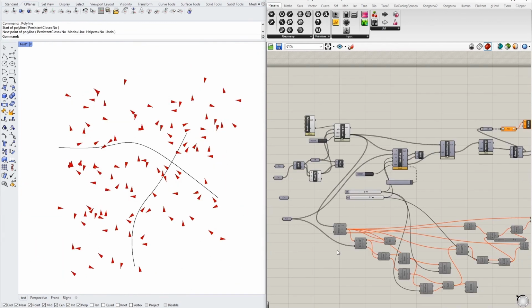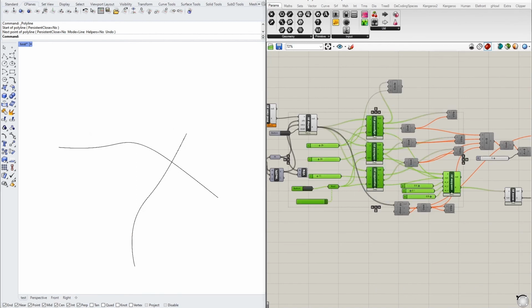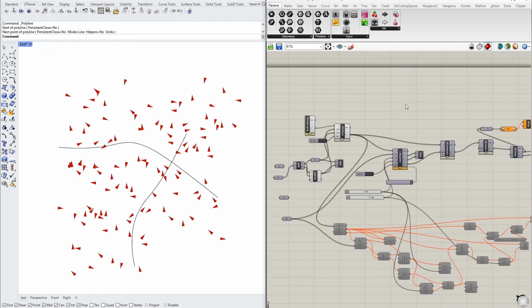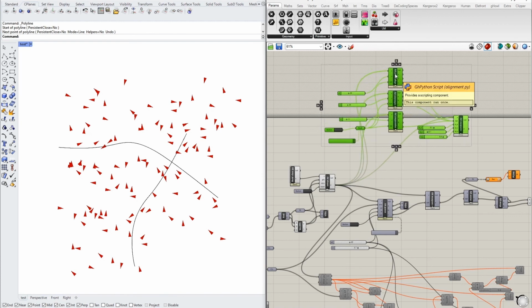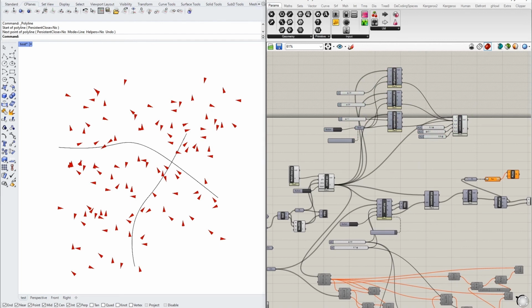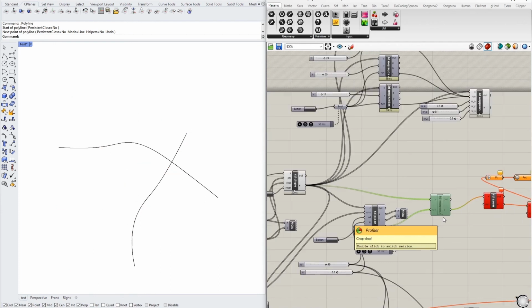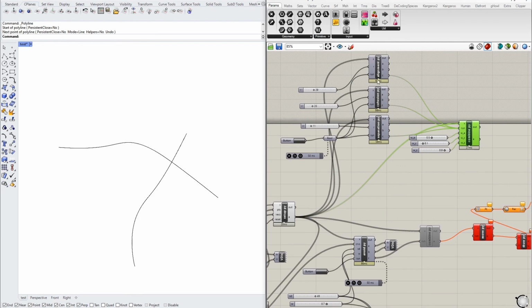We can now combine it with the exercise that we did in part 2 with the Boid's behavior for alignment, cohesion, and separation. We will make a copy of the alignment, cohesion, and separation process and the associated sliders into our new file. We will now disable this combine node and edit the combine node from the separation, cohesion, and alignment to include the vector avoid. And we will reconnect some of the pieces here.